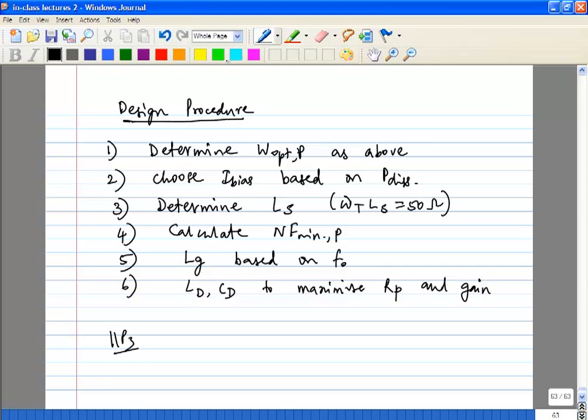The other thing we didn't talk about was IIP3. The reason is, obviously we know that the MOSFET is a short channel MOSFET. It doesn't behave in a square law manner and so on. So it is not that easy to do a hand calculation of IIP3, because it's going to be quite far off from your simulation or measurement.